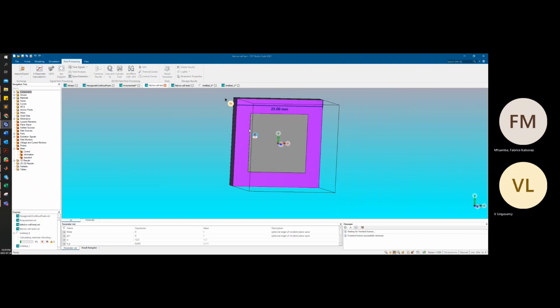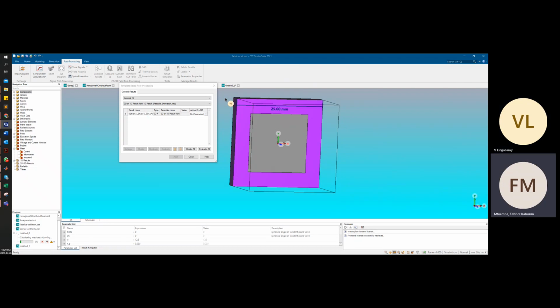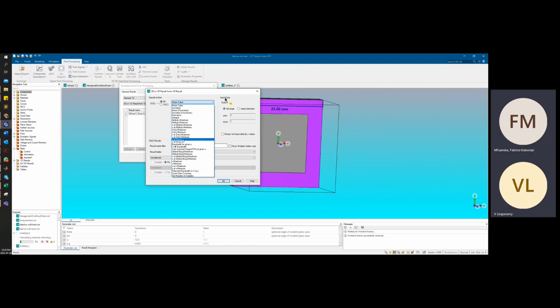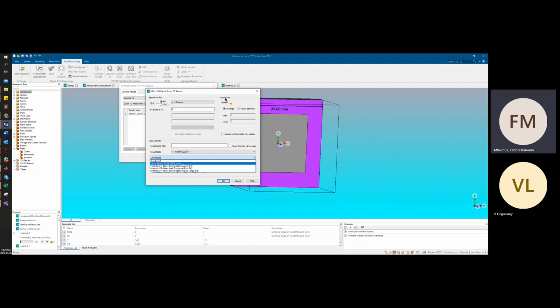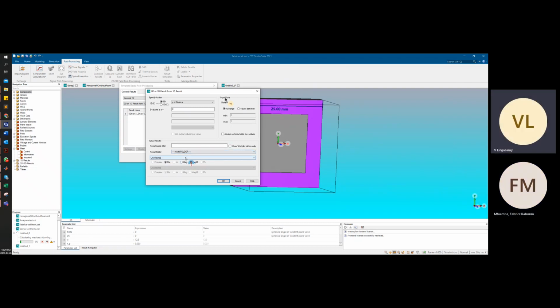For example, I go to post processing, and choose 0D, 1D results. Then I go to Y at Y given X, and X is frequency. I choose some parameter, because when you simulate, you will get those parameters. Then for this one I can choose the magnitude, phase. Is it right? Yes, exactly, correct.